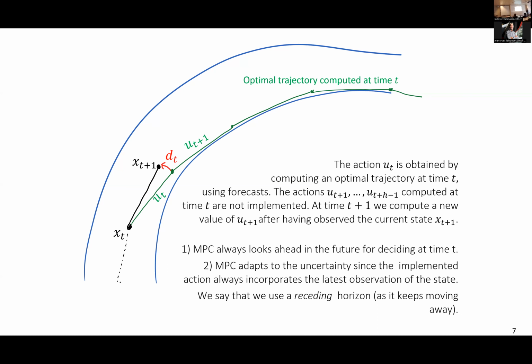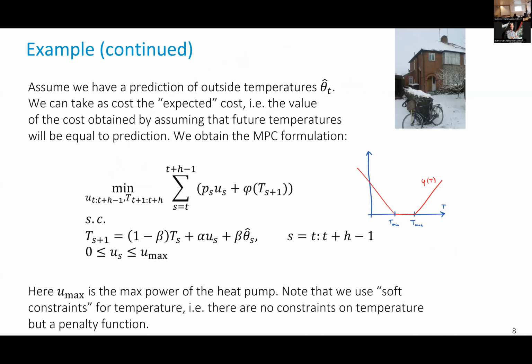So back to our much easier system here. Since we have a fairly accurate model of the house, this is easy to have because we're just modeling a house and not the universe or the weather in all continental Europe, we can solve the problem, and that gives exactly this. So I take a horizon. My disturbance is the outside temperature, so I predict it.